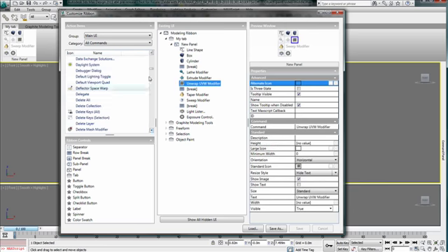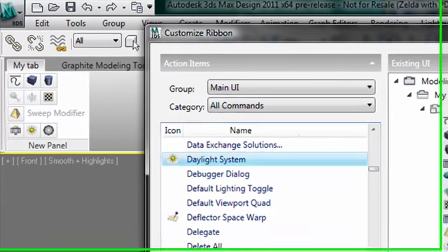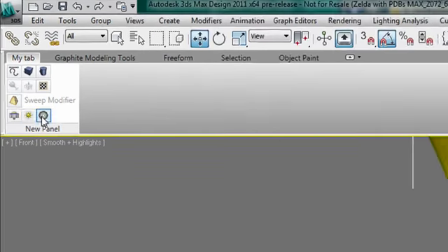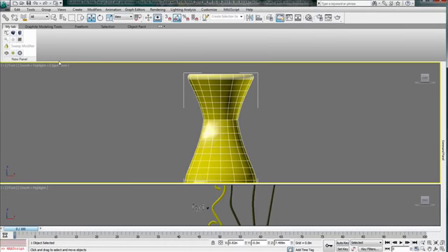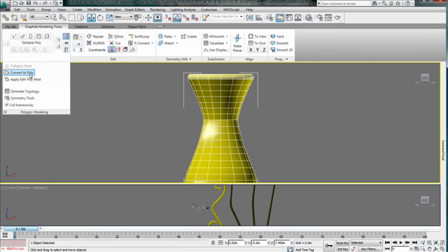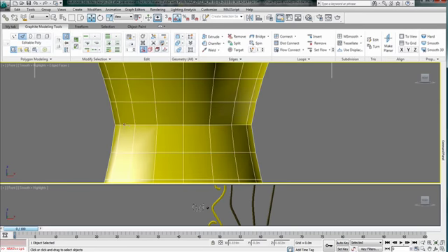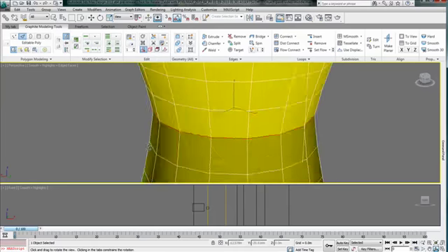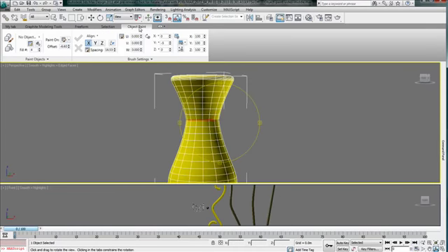With the ribbon customization, the ribbon is not limited to modeling operations anymore, but can be used to create many different task-based UIs. Whatever task you are adding to the tab or panel will display automatically in your ribbon. Back to my decorative pot, let's transform it into a poly to have access to Object Paint. Under my edge mode, you can now select two edges in a row while holding Shift, and the complete loop will be selected, allowing for fast interaction.